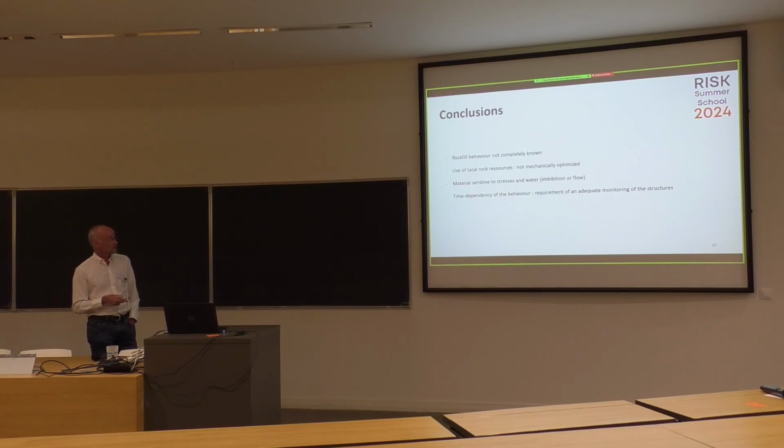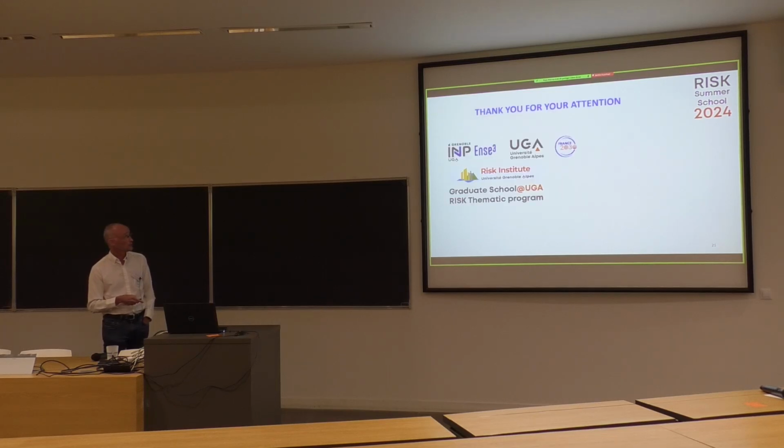The rockfills are very sensitive to stresses and water, imbibition or flow. And the problem is that we have to monitor, it's a very important requirement to monitor these very huge dams to follow the evolution of these structures with time. Not only the settlement, but also the flow of water inside. Thank you for your attention.